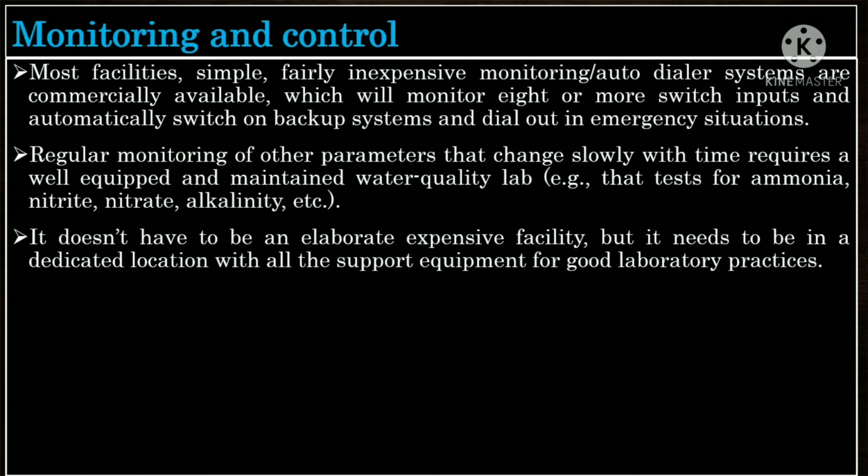Next is the current system engineering design. There are several alternative solutions to each of the unit processes utilized in intensive recirculation aquaculture systems. The important design questions that determine what unit processes to use include the species to be produced, the stocking density, production capacity, and the sensitivity of the species to water quality parameters such as temperature, dissolved oxygen, ammonia nitrogen, pH, and carbon dioxide, which is CO2.